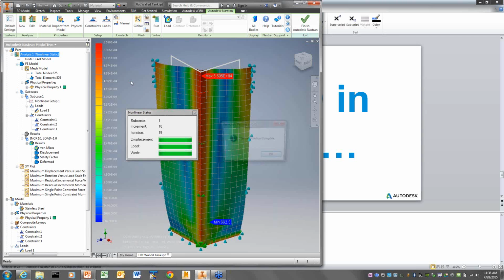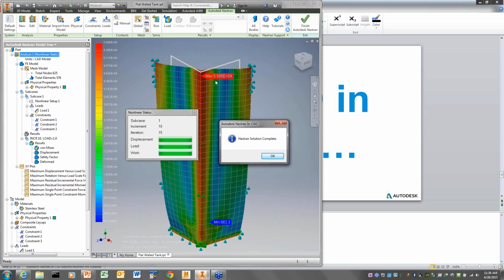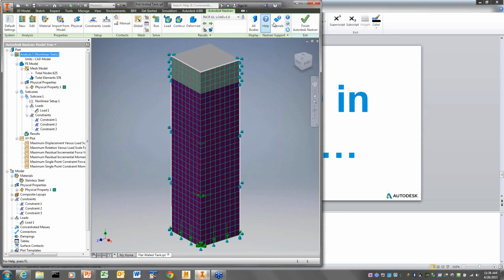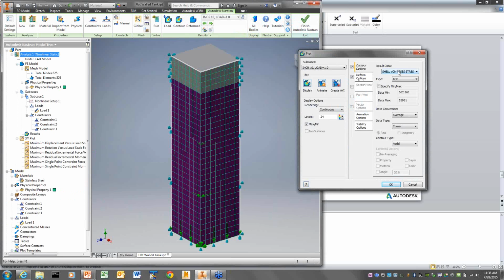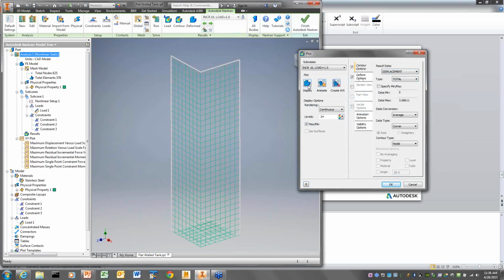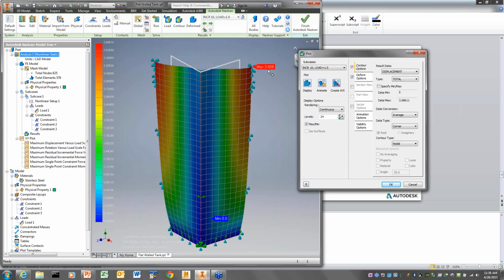And now you can see here, before I close this little window, the von Mises stress is now about 55,000, and 55,000 is a whole lot more what I would expect if it yielded a little bit. My deflection has not changed, which you can see if I go in here and plot my displacement. My displacement is basically still 3.7, so adding plasticity hasn't changed it.